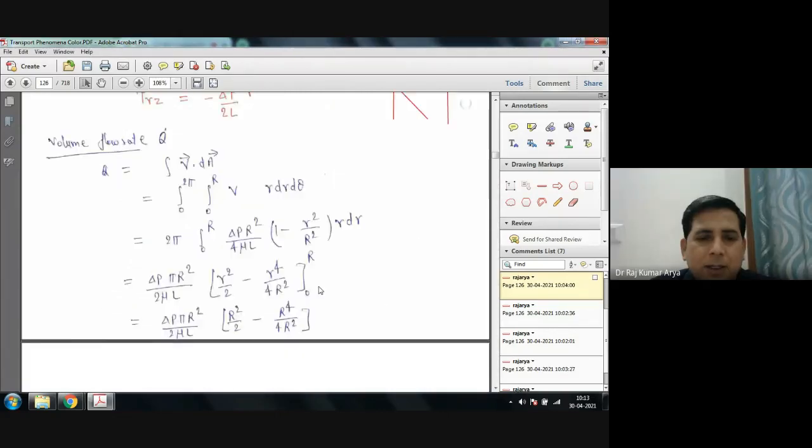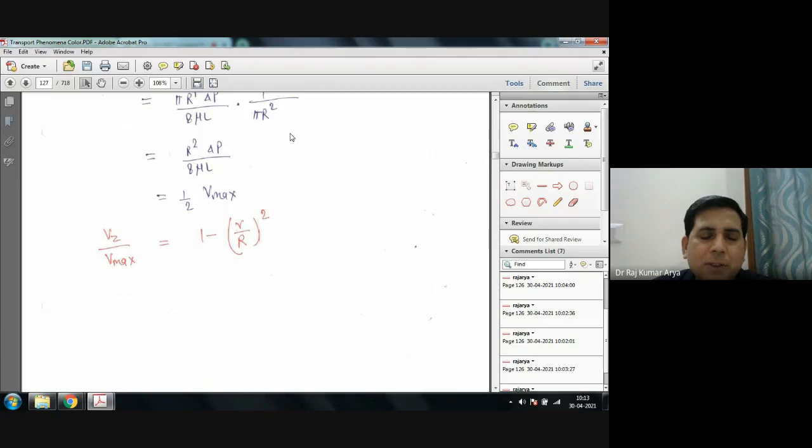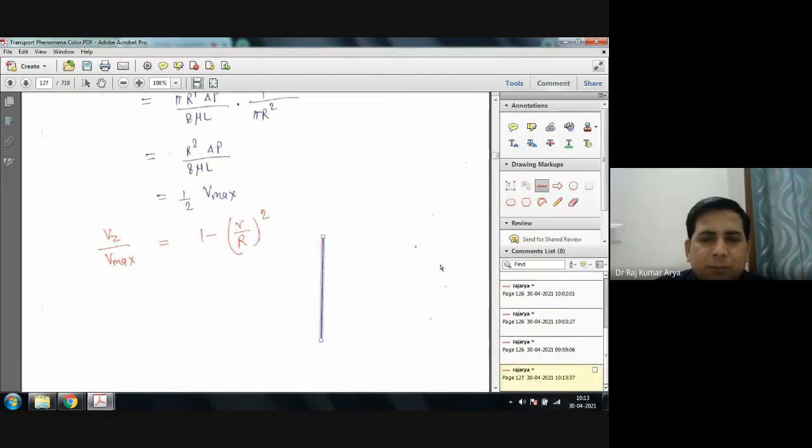Now, this is all about a Newtonian fluid in a pipe. What we have found here is the velocity expression and the expression for shear stress. The velocity distribution you can calculate from here. How would it look? What type of velocity profile would it come out as? Any idea? Yes, it's parabolic, because here you have power 2. So it would be a parabolic profile.